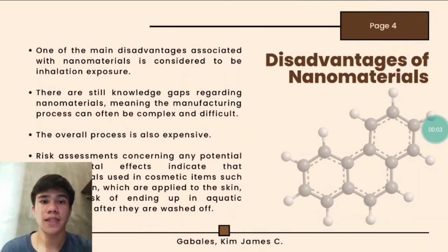If there are advantages of nanomaterials, there are also disadvantages. First, one of the main disadvantages associated with nanomaterials is considered to be inhalation exposure. It means that nanomaterials can be a risk to our health because some nanomaterials, such as carbon nanotubes and nanofibers, may cause pulmonary fibrosis. Other health risks are ingestion exposure and explosion hazard.